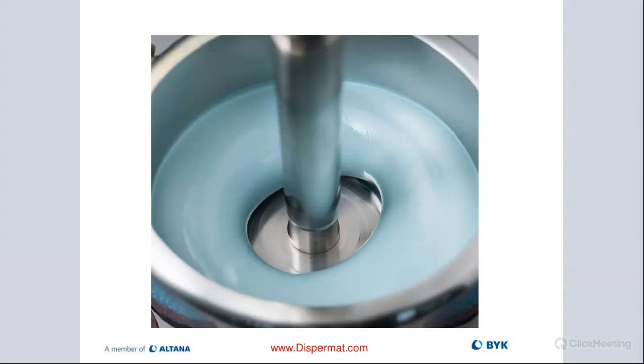And here's a nice photo of a donut. You should see the actual blade exposed. You can see the center of the blade as it's dispersing our mill base. And if we have an optimum viscosity, we should actually see a really nice donut being formed. That's the visual cue that tells us we're doing a good job, we're putting in energy, and we are now really in the process of properly deagglomerating our particles and turning them into aggregates. So this is a very nice slide here.